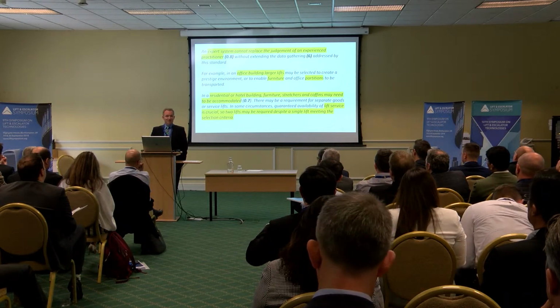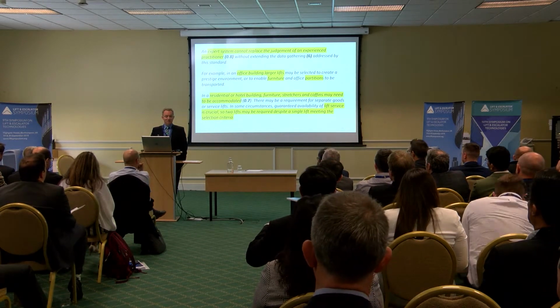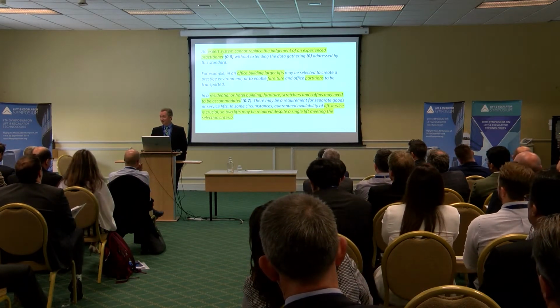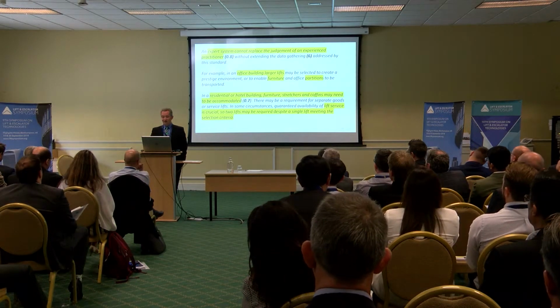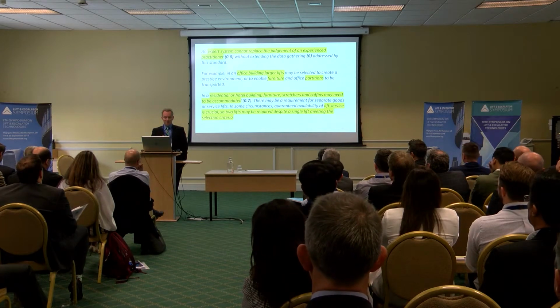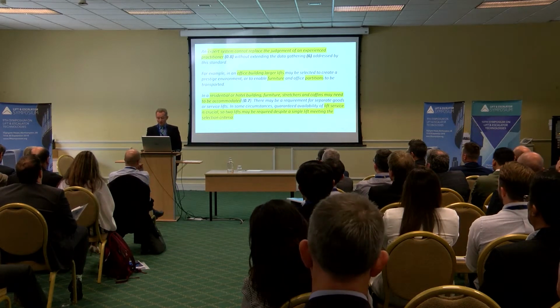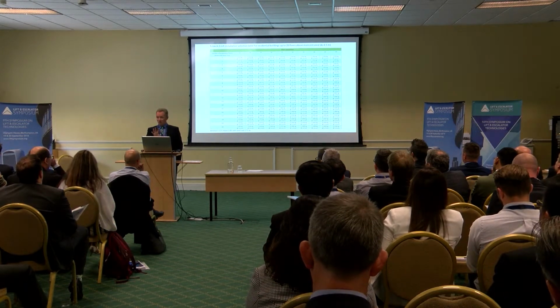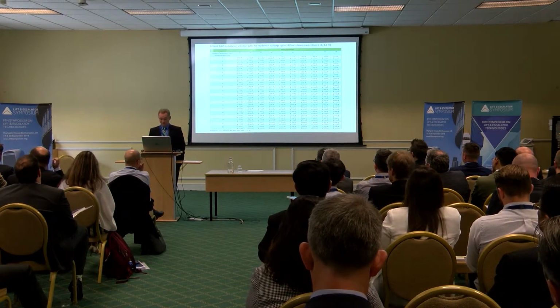And you might have an instance where the lift service is absolutely crucial, so you can't afford not to have a lift there when a lift goes out of service. So you might put 2 in, even though the calculation says you need 1. So these tables don't actually address that. They give you the minimum, and then they're still requiring some expertise from the user.